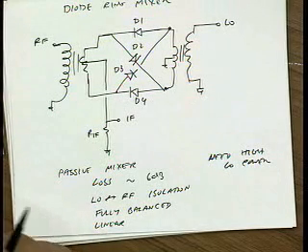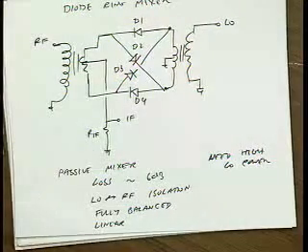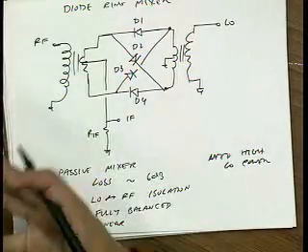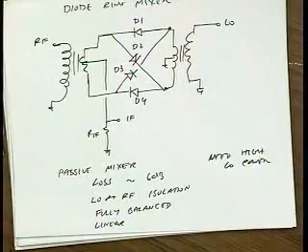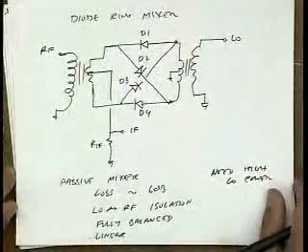Compare that to a MOS device. In a MOS device, we had to drive lots of capacitance. We still had to pay for it, right? It's not for free. Even though the capacitance is reactive, we don't have infinite Q circuits. So finite Q means we had to also pay for the LO power that way. Okay? Questions about this mixer? I'm going to describe the operation in a second.